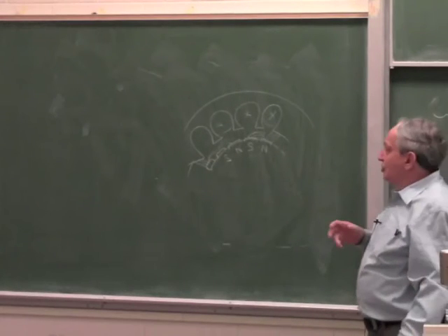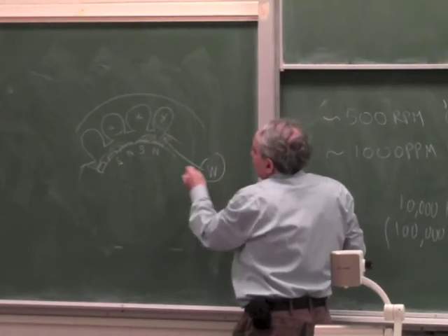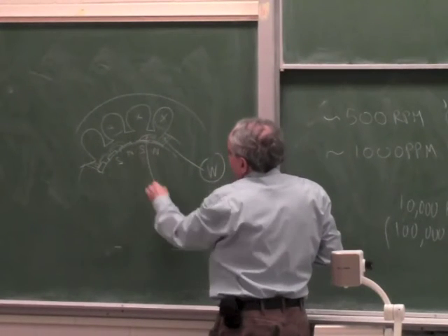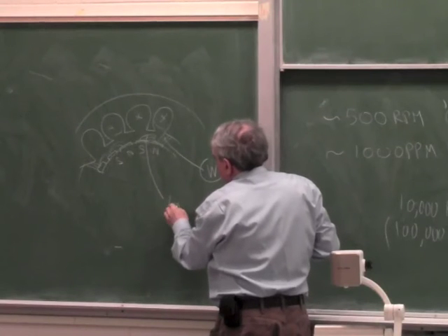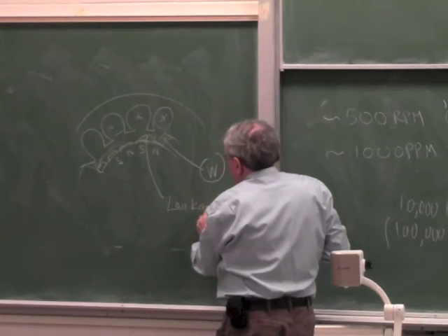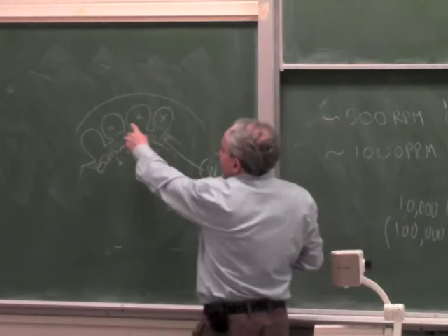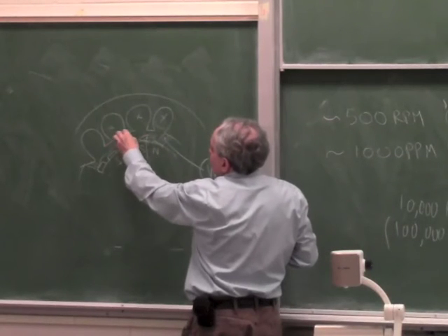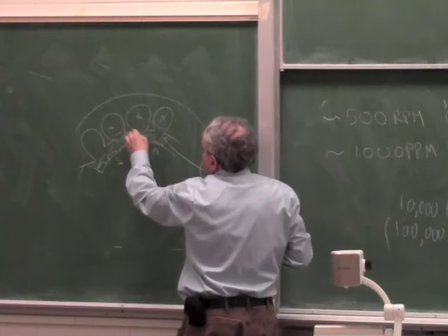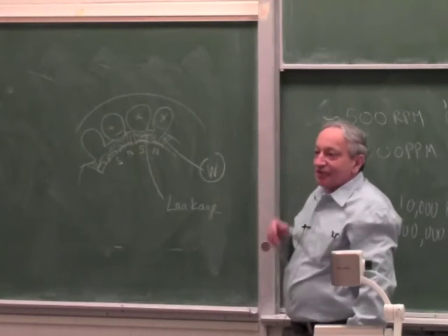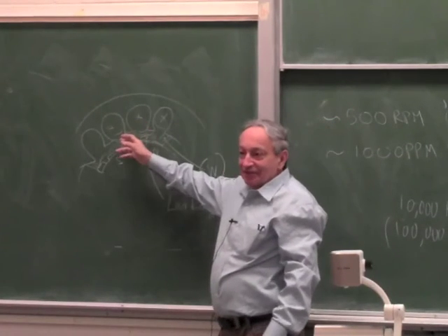Now, the ratio of the flux which does the work and the flux which is just wasted, this is waste or leakage, this determines the efficiency of the motor. Because think of this side. This side is supposed to generate flux going to the rotor, but it also generates flux which is shorted by the air gap. So this flux that you short still needs current to make it.